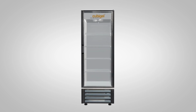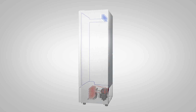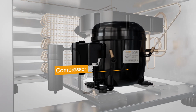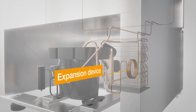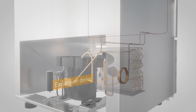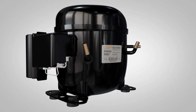To convert a commercial refrigeration system that uses HFC refrigerant to propane, as well as change the refrigerant charge, we must replace the compressor, filter dryer, and expansion device, which can be an expansion valve suitable for the R290, or in our case, a capillary tube. To change the original compressor, the first thing that we have to do is determine the equivalent propane compressor.